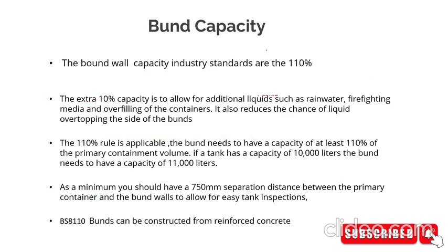Bund capacity. How do you calculate and construct the bund? The bund capacity industry standard is 110 percent. This is the industrial standard capacity.